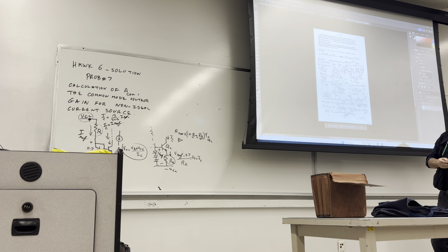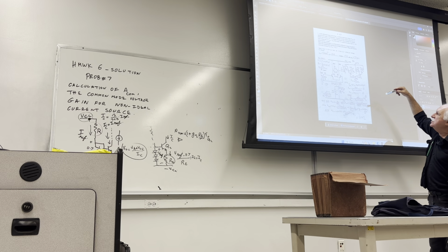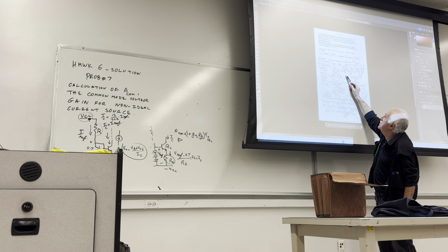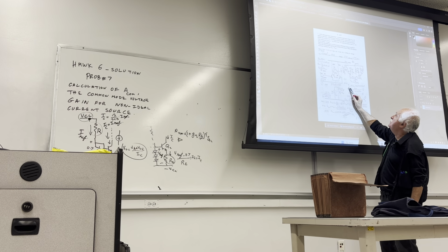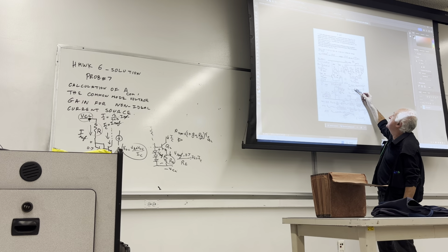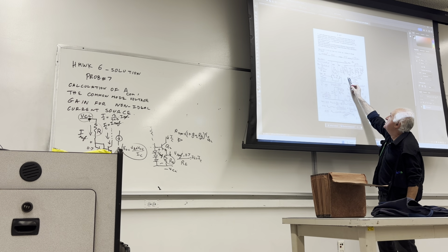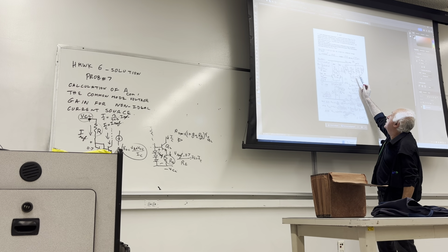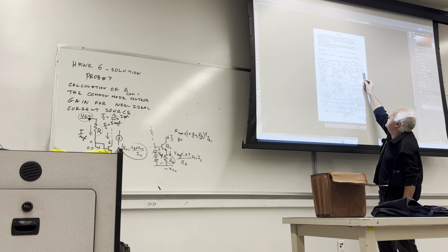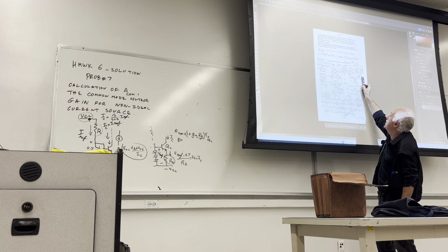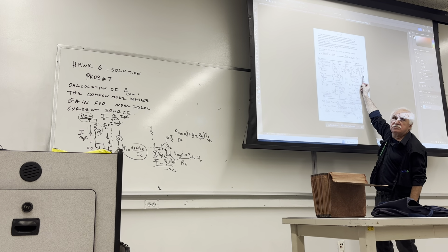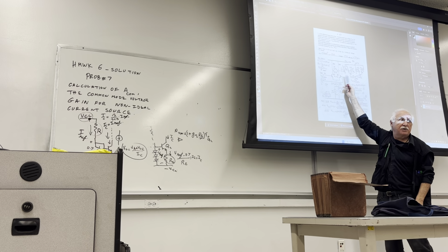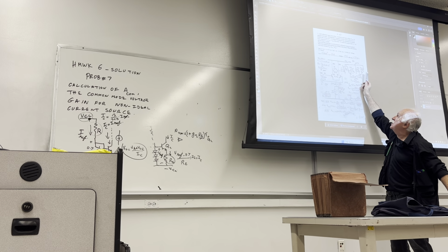Now, how do we analyze it? Take a KVL, VCOM, so it's this voltage, negative to positive, that's the VCOM. R pi times IB is the voltage in the transistor Q1. There is also another IB in here for the second transistor. The two are equal IBs. Why are they equal? Symmetry. This circuit is completely symmetrical, so you get two identical IBs over there.